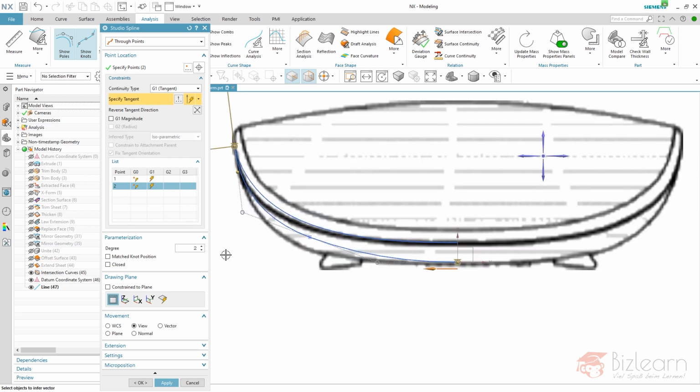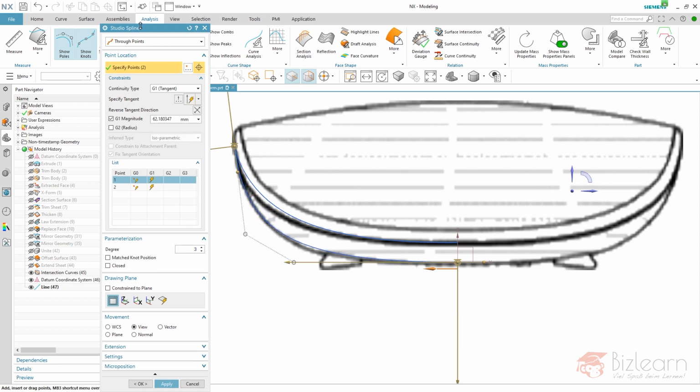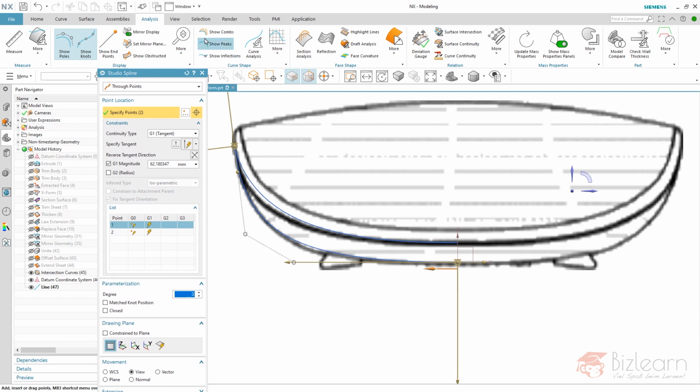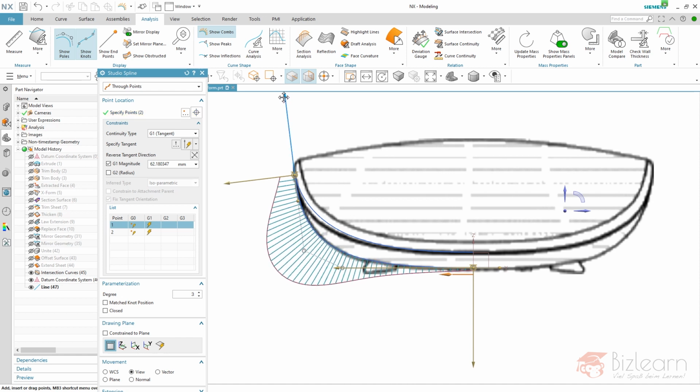And of course, we need some modification. Here you can see a knot, because we have 2 poles here, meaning 4 minus 2 is 2 segments. If I increase, we get 1 segment. And what I'm going to do now is move my poles like this and this one by right-clicking one of my start or end positions, specify constraint, and now you can easily move your poles like this. Pretty simple to do. But I'm also going to check my curves. I'm going to check my combs here because I want to make sure this is still smooth enough. And you can also increase here like this.